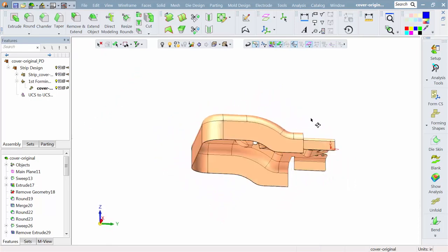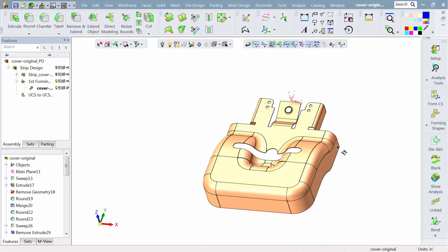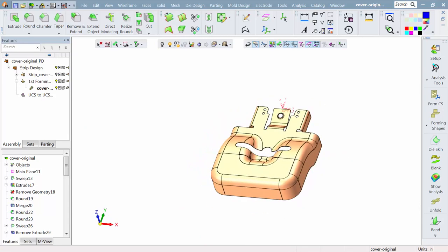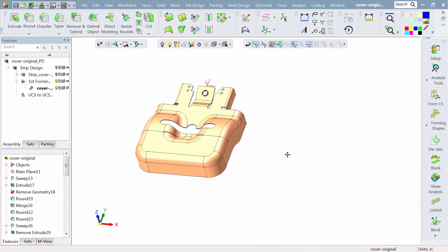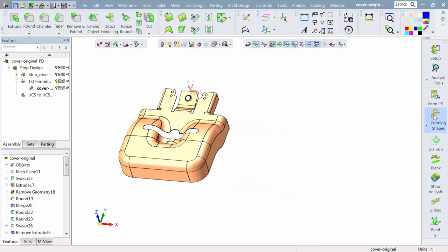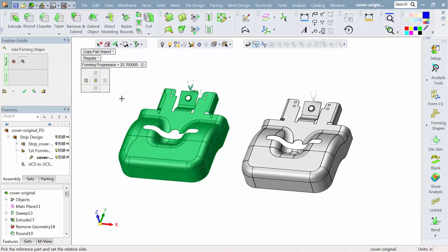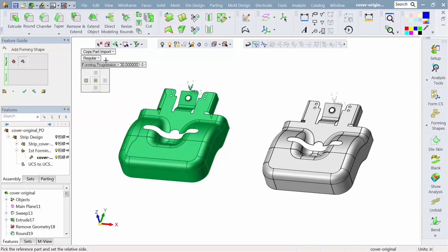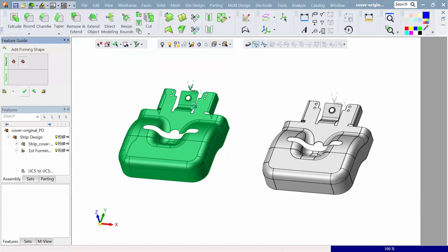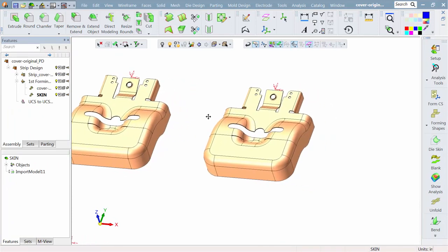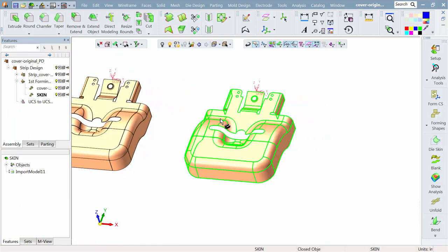Well, with that, we've got a pretty good understanding of what the part looks like and what it's going to do. So we understand some of the requirements now that we need to deal with to unfold it, form it in a strip. So let's begin working with the part. Here I'm simply giving the next station a name. The idea here is if I wanted to, I could set my distance, not necessarily the progressive distance of the strip. Also, if I wanted to mirror this, I could, to create right hand, left hand for a 2 out in that sort of situation.